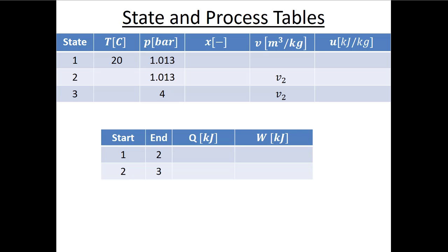Now, there's always kind of two choices, right? We talked about how these problems in thermo are a bit like a choose your own adventure. Is the system open or closed? What's the fluid? What happens to the energy? That's part of what you're doing. Another big decision you're going to have to make is, should I do the whole problem symbolically to get equations and then fix the states at the end to get numbers? Or the other option is, I've got this state table, let me fill in all the information that I need on the state table, right?